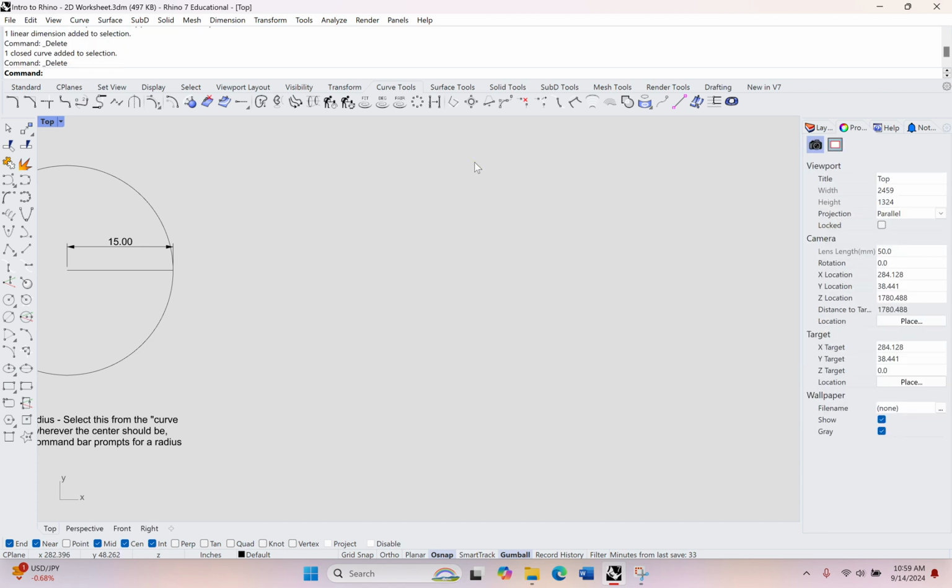This also applies for creating, let's say that you wanted to create a single line of a certain length. I'll grab the single line tool, place my first point in the workspace, and then I'll say I want a 20-inch line. So I type 20 in the command bar, and it locks the development of that line at a certain point. I can check my work with DIM. There we go.